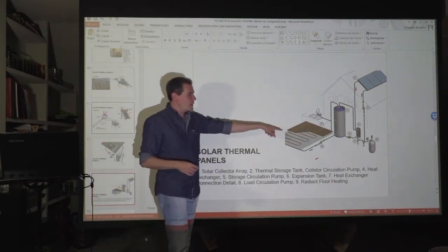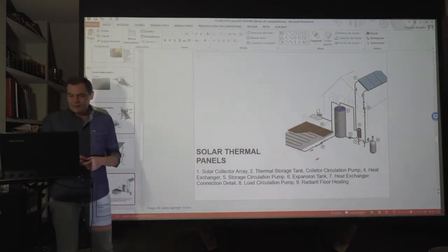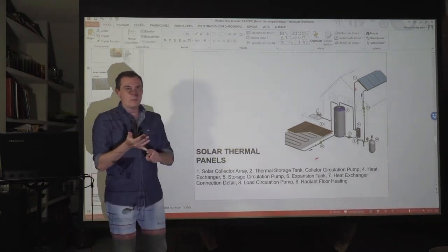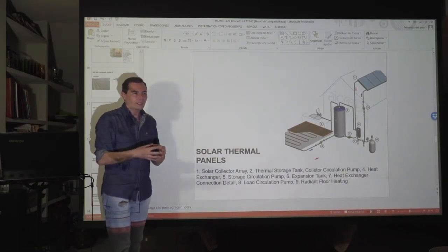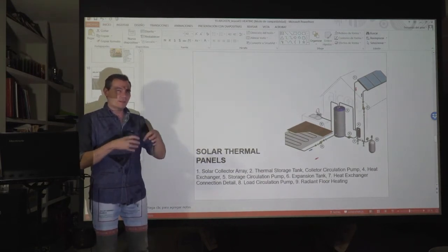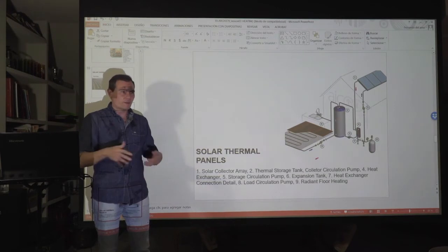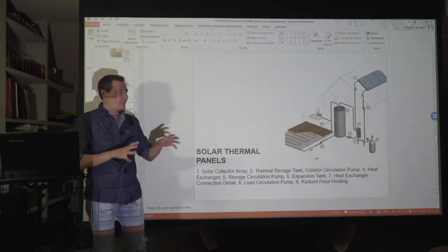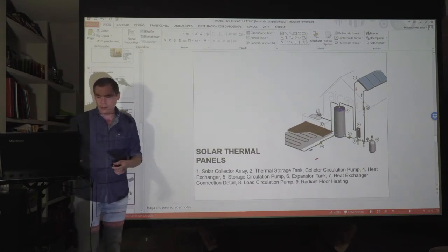And then we can use this for hot water, or we can use this for radiant floors. Sometimes we combine things, so don't think that we have to use either a pellet boiler or a gas boiler or solar collectors. You can use everything at the same time. And in good buildings, we have different energy producers, because especially with solar energy, if we don't have sun for 3-4 days because it's raining, what do we do? So we need a backup boiler. So combining gas boilers, condenser gas boilers with solar collectors might be a good idea.